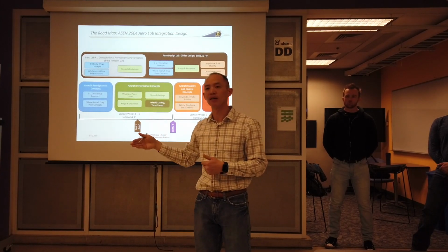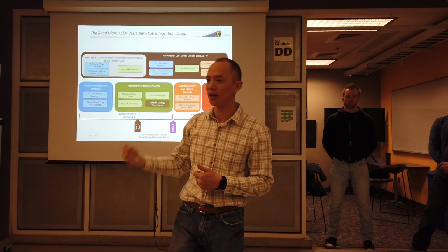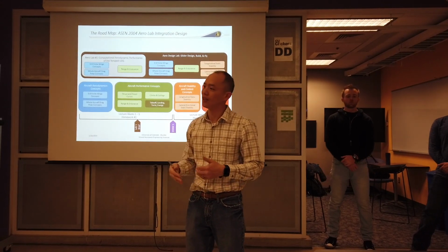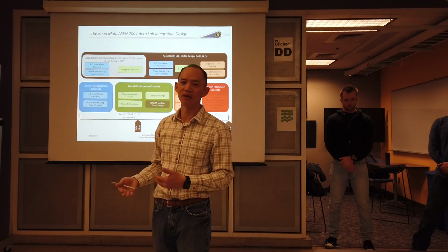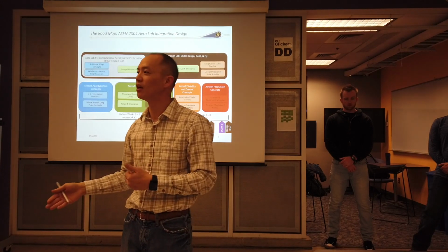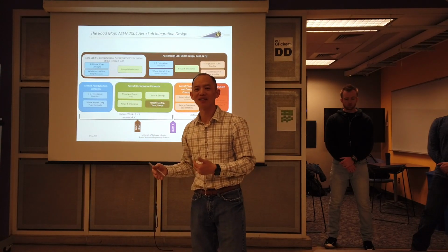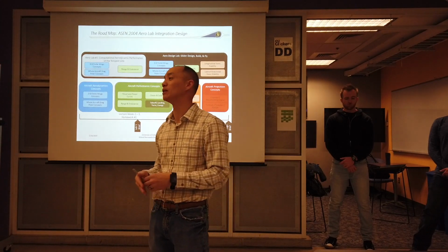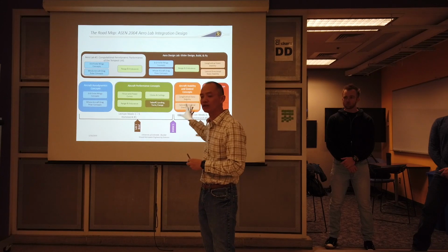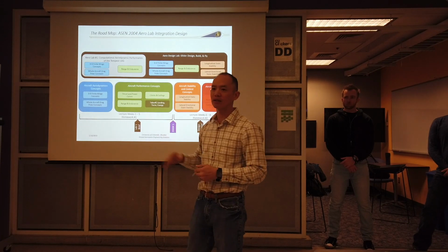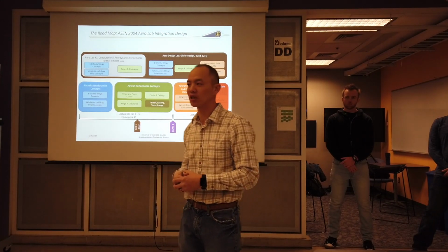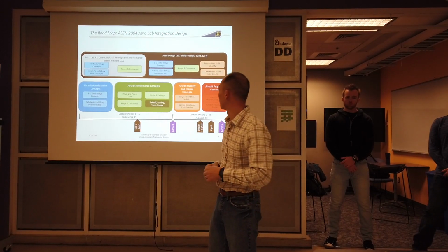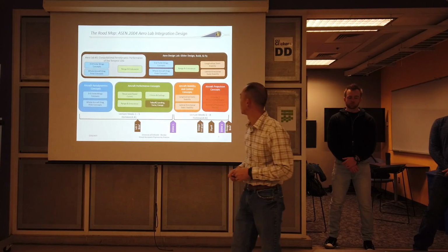The one add-on on the second part is that we're going to make sure you understand the basic concepts of stability, so that even though your aircraft has a great wing, it has the lift necessary, has a great L over D, so it predictably has a good range. If you throw it and the thing stalls immediately and then does a death spiral into the ground, obviously you're not getting very far with that airplane. So you need to have some basic understanding of stability control, be able to estimate that for your airplane and make sure that when the first time you throw it, it at least in general is stable. And there's always going to be some wiggle room there. We'll talk more about that for the design lab when we get to it.